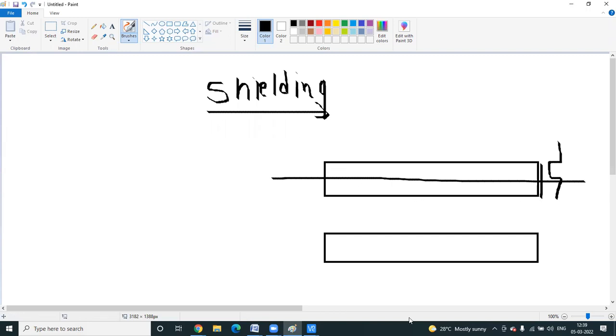Okay, so these are near each other. What is capacitance? C equals epsilon A by D. Another one is connected to some NMOS, two metals connected. Due to this, what is happening? A parasitic cap will be formed. Parasitic means a nearby adjacent cap, which is unwanted. Noise means unwanted signal. Similarly, parasitic cap is also unwanted.